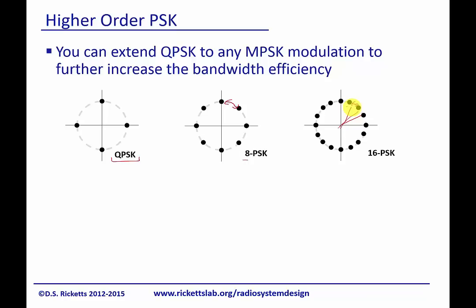And if you're wondering why that matters, you can probably think that any physical system isn't going to be quite perfect, and these dots will actually be little fuzzy balls just due to noise in the channel. As our signal gets weaker and weaker, we can put an amplifier on it, but these will actually get larger and larger.